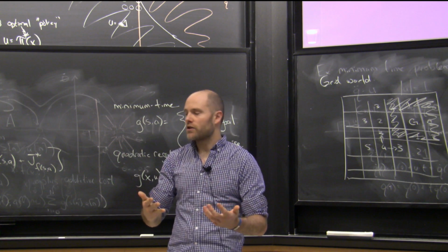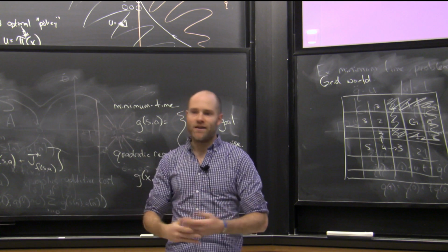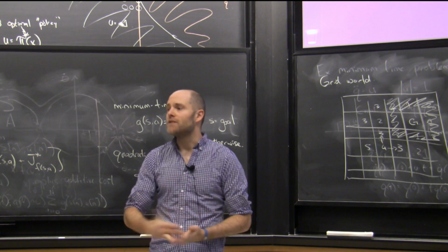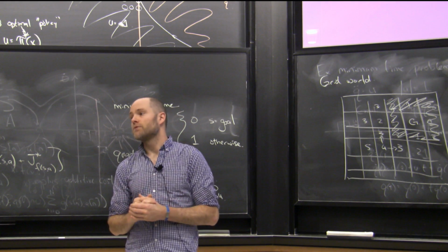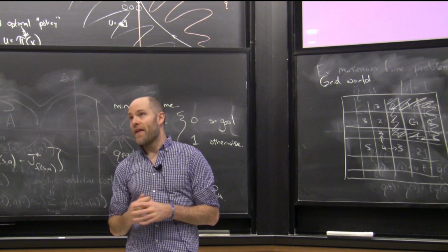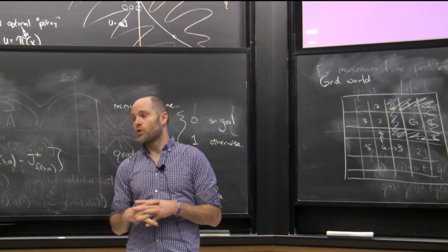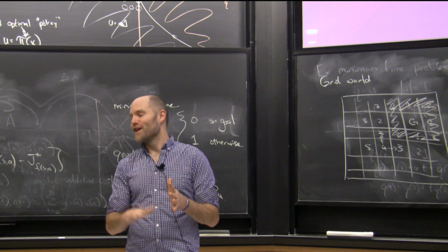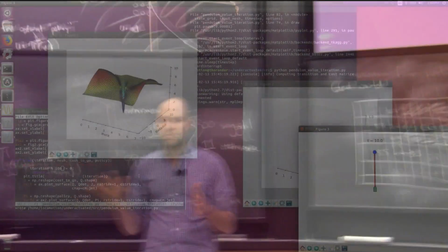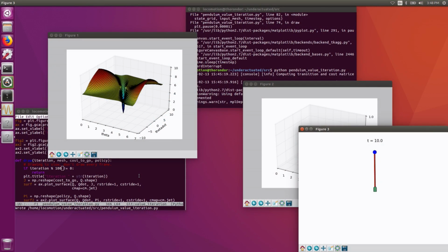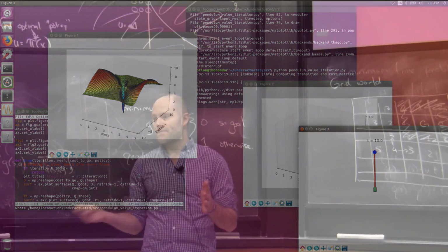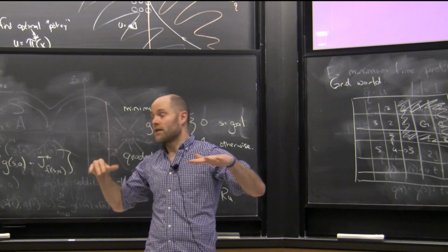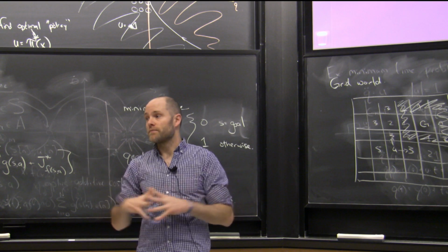And you could put in your cost function something like exploding is bad, or falling apart, running into walls is bad. If you can solve that problem, which you can't always, then you should have some sort of guarantees in the real world. And that is roughly the stuff of robust control: how do you put in the known unknowns, if you will. You try to put in things you suspect about your system, but you don't have quantities for, and you try to say, for all of the things that might have happened, I'd still like to have some bound on my total performance. That's a more complicated version of this, but it fits into this type of framework.